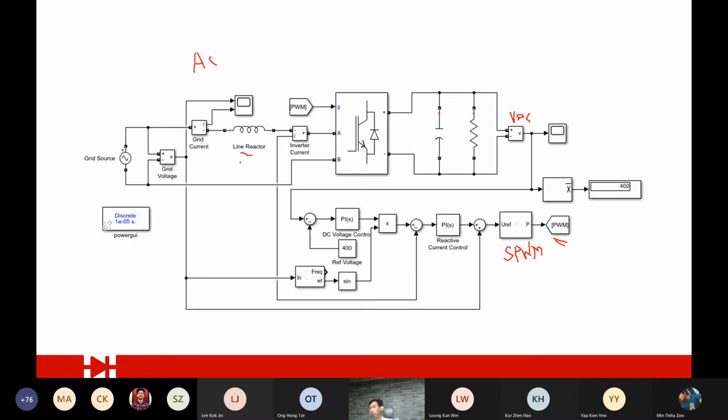You see, it's just like an inverter, but it's not inverting from DC to AC; we switch it to rectify, from AC to DC. Sometimes you don't look at this and say, oh, this one is surely an inverter. No, not necessarily. That's why with good proper control, you can make a bidirectional inverter. You can rectify, you can invert. So we call it bidirectional.